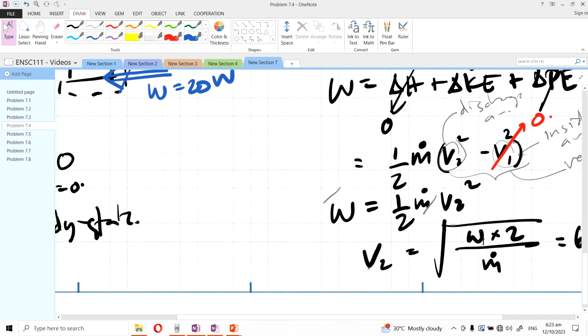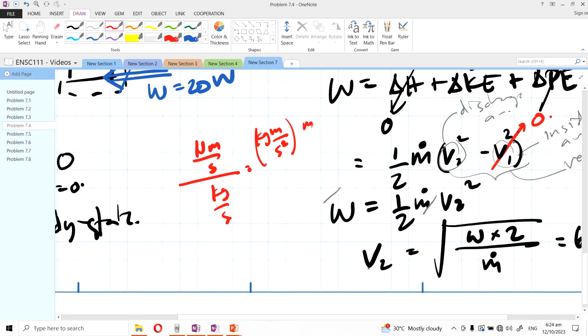So to check, this is a unit of power. So the unit of power is Newton meter per second, right? Times 2 divided by the unit of mass flow rate. Mass flow rate is kilogram per second. Okay, so next is, what is Newton? So it's kilogram meter per second squared, right? Times meter per second, and here kilogram per second.